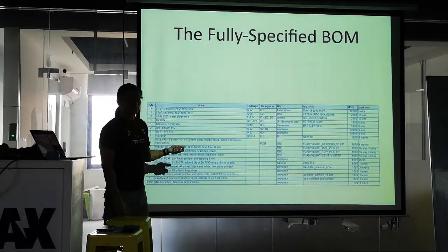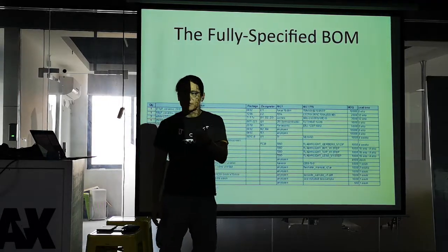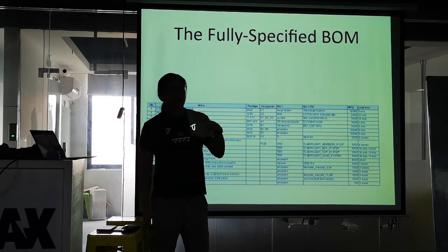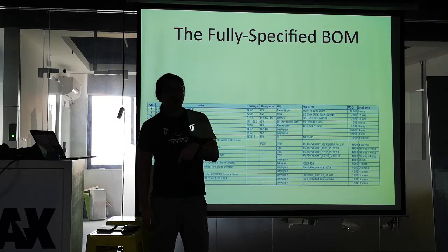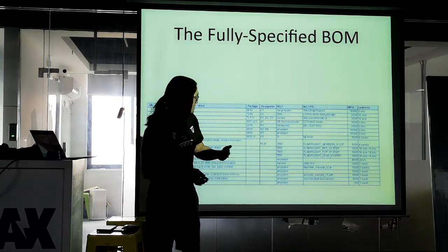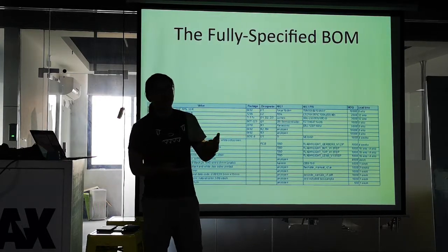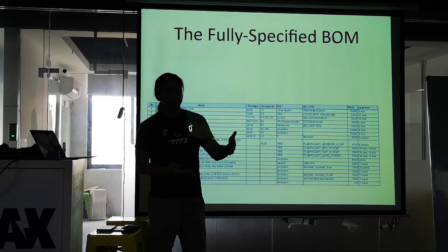One of the weird things about tools like Eagle or Altium is they don't put the PCB on the BOM, right? You'll get the output and it'll be all the electronic parts that go on the PCB, but it's somehow implicit that the PCB is going to be built. If you send your bill of materials to the factory without the PCB as one of the things you want quoted, they will happily quote for you without the PCB.